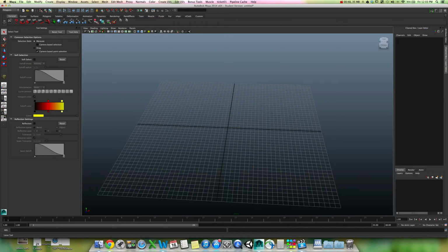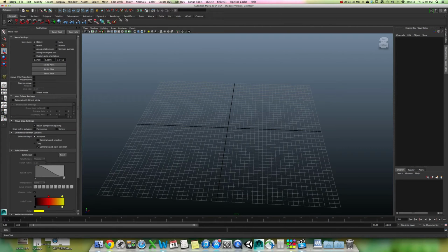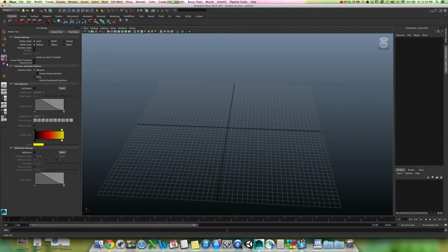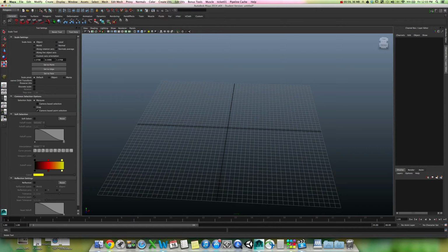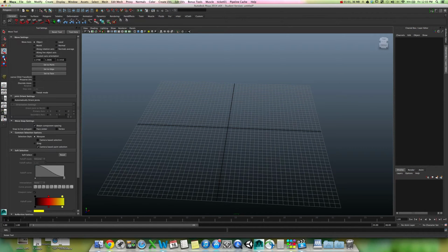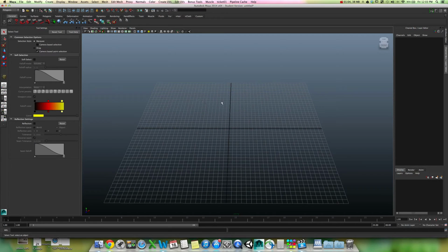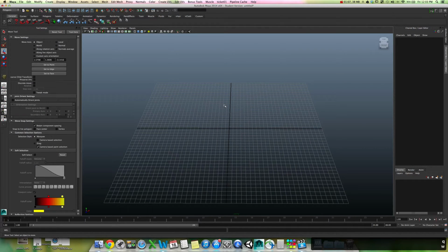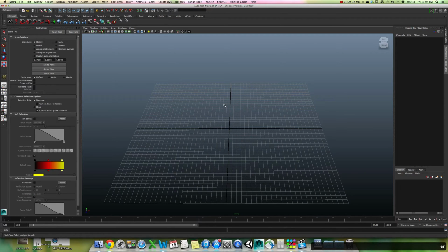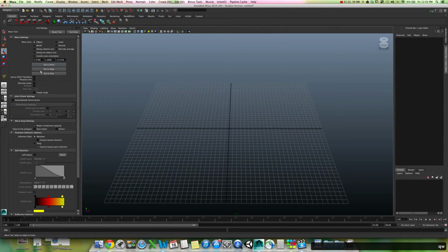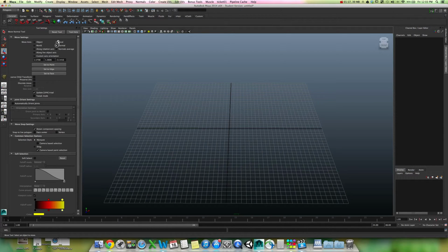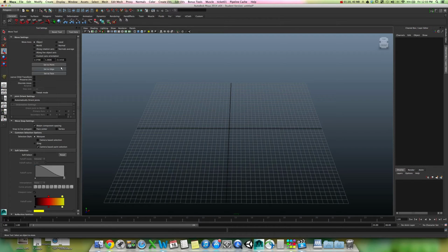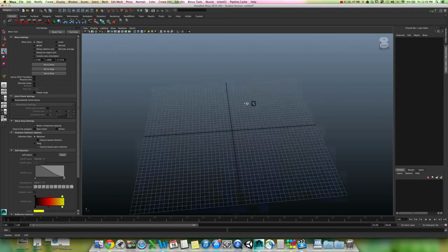Alright, so let's just go on a really abbreviated tour of our interface here. The first thing you'll see in this left-hand corner is select, move or translate, rotate, and scale. Those are our primary transforms, what we'll be focusing on today. Now the hotkeys for these are Q for select, W for translate, E for rotate, and R for scale. And you can see what's happening over here. This is your tool options, and we'll go over these in a second. All of our basic local object and world space coordinate systems and how they vastly differ from one another in the results.